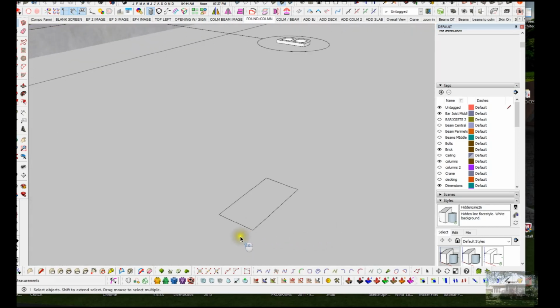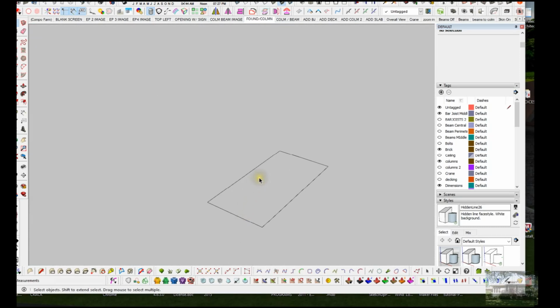What I want to do here is create the profile of the eye section, if you will. So we'll use the tape measure tool, or run over and find the center, and we'll go over a quarter inch each way from that. So we create a 1/2 inch thick web. I like to use guidelines because this way I can draw it out and make sure I know what I've got before I commit to anything solid, concrete.